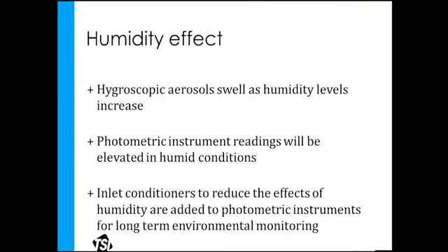So if you're doing long-term monitoring, especially outside, there's inlet conditioners that can be added that will dry out that aerosol if you want to dry it down to 30%, 50% or something like that to normalize the weight. So when you do gravimetric sampling, there's humidity conditioning involved too. The lab that's going to give you those samples pre-weighs those filters in a humidity conditioned chamber for 24 hours and lets the humidity balance out. And they weigh them, they send them to you, and you take them to the field and sample them.